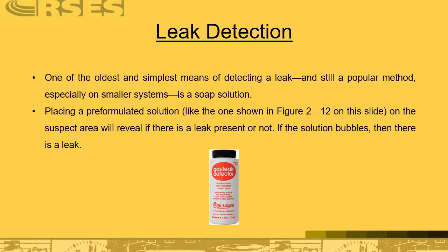What I happen to love about the ultrasonic leak detection method is you don't put liquid on anything. Basically you're using a microphone and listening for a change in the noise level at a suspected leak area. And once you start utilizing an ultrasonic leak detector with headphones, I can pretty much tell you you'll never go back. Those things work great.